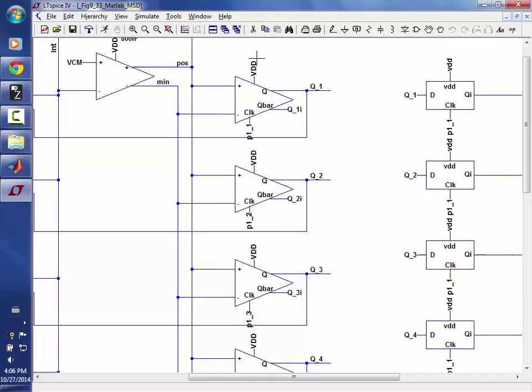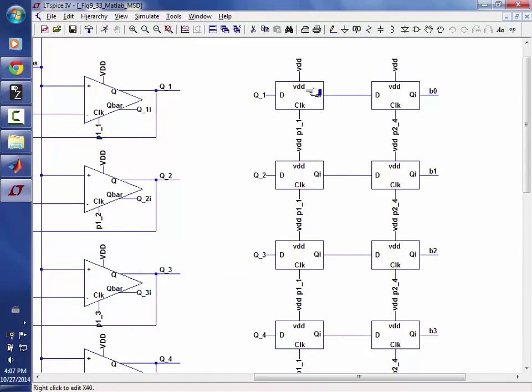Anyway, we'll cover this stuff in more detail, but the digital part, just pretty much common sense. What's that? No, if you clock them at the same time, it's not going. There's a delay through here, right? So the output's not going to change until after the delay. However, you're capturing the previous value, which means you have a whole clock period for the output to settle.